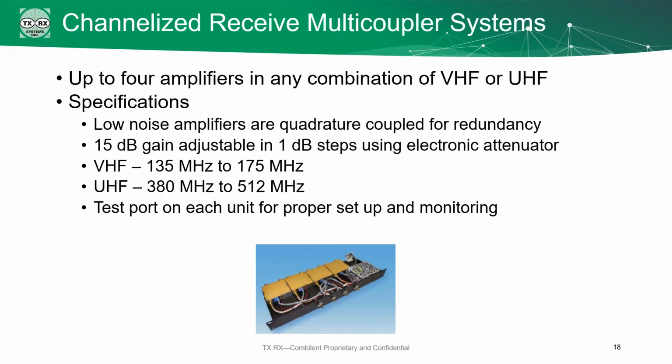Again, they're low noise amplifiers, they're quad coupled for redundancy, and we still have our 15 dB of gain adjustable in 1 dB steps. Each amplifier has its own test port for proper setup and monitoring. Each amplifier operates independently of the other amplifiers on the deck.